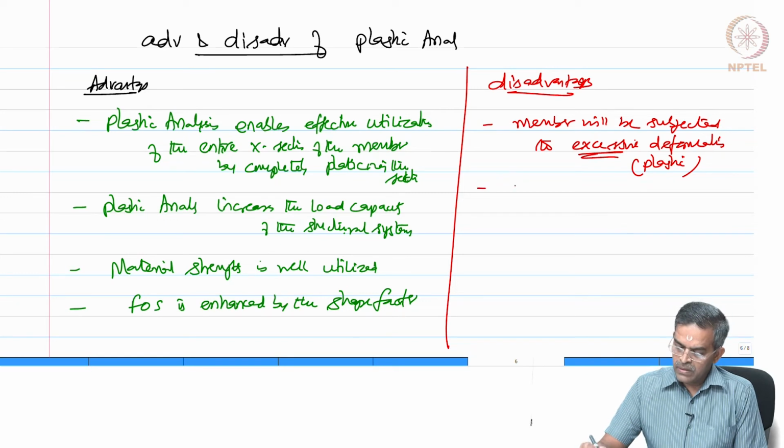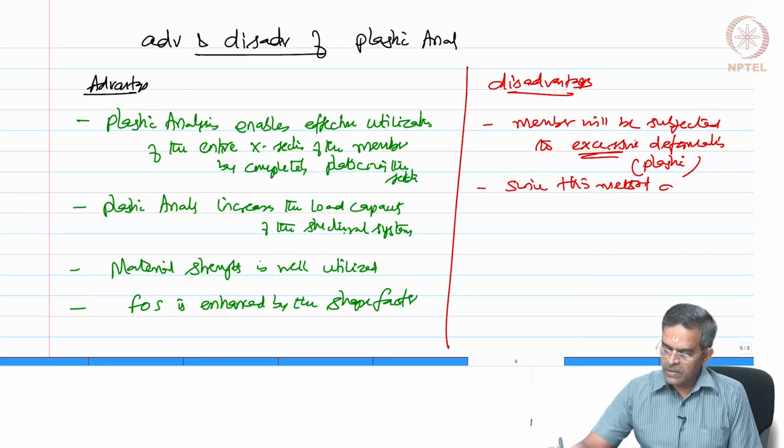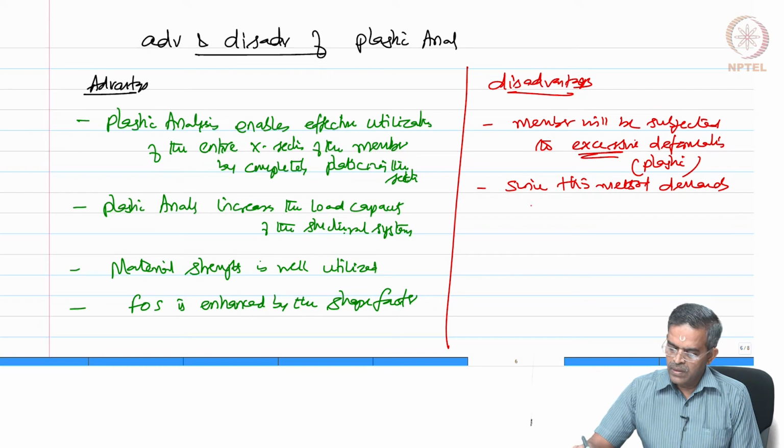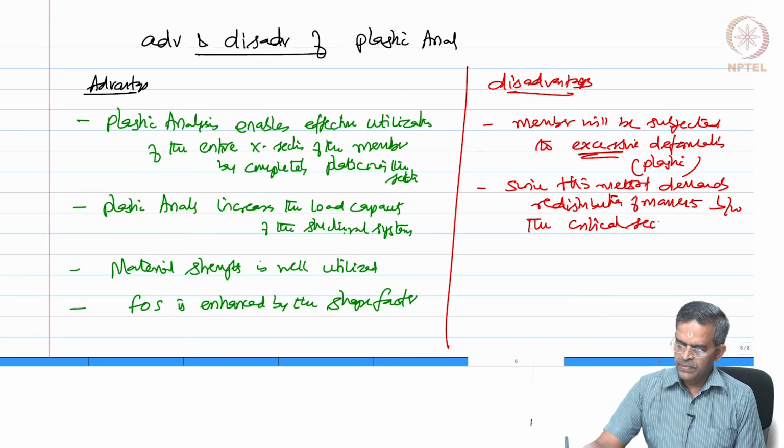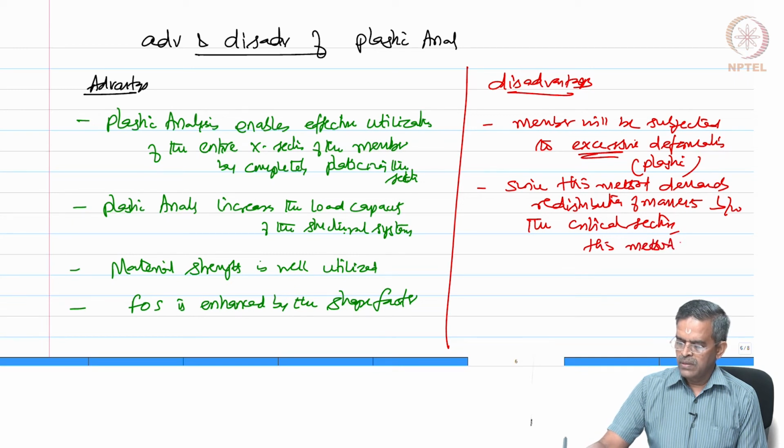Since this method demands redistribution of moments between the critical sections, this method is useful only to statically indeterminate structures.